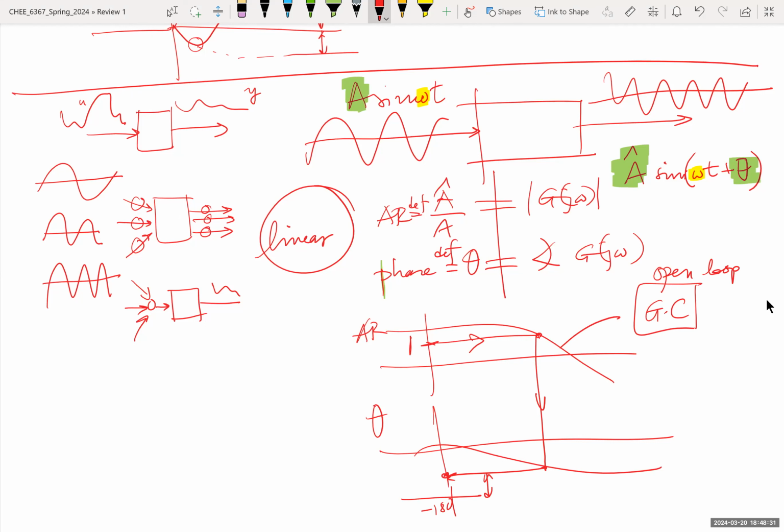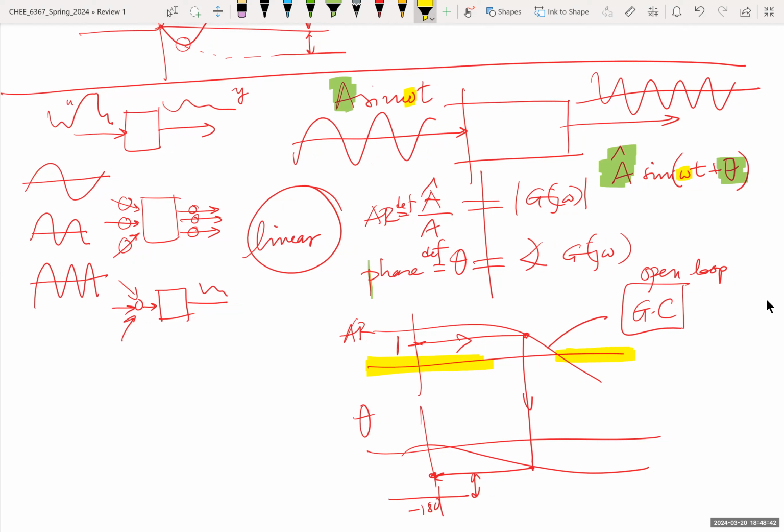But more important is the filtering properties that one can understand from frequency response. These frequencies to the right are filtered out. These frequencies to the left essentially go through. From these frequency ideas, we can understand how noise and set points, even though they correspond to exactly the same amplitude ratio, differ: the set point has frequencies in this range, noise has many frequencies here.